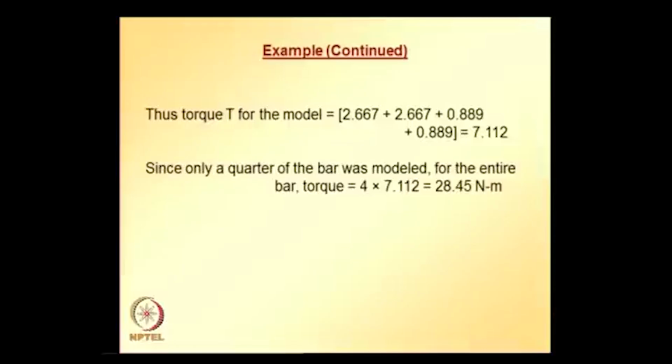Also, this problem can be solved exactly. The exact solution is 36 Newton meter, and if we compare with the value that we obtained, 28.45 Newton meter, with 36 Newton meter, it can be noticed that there is 21% error, and that is because first of all we used only linear elements, and that too we used only 4 linear elements.